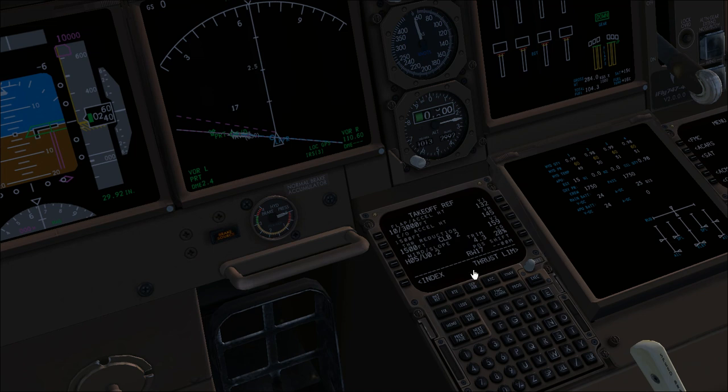Before moving to another section and actually finishing with the procedure and finishing with the takeoff ref, I want to show you a pair of more pages in the CDU that are probably more important because they are different from the 737 we're ready to fly. First of all, to change the transition altitude and the transition level, you must go to the VNAV page, and as you can see, transition altitude for climb is indicated in the climb page, and if you go with next page, you see the descent forecast like in the 737, the transition level is in this one.